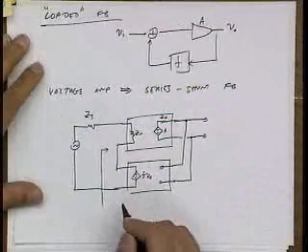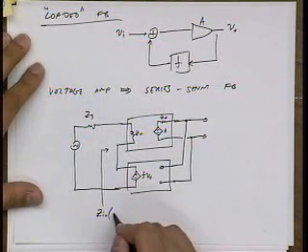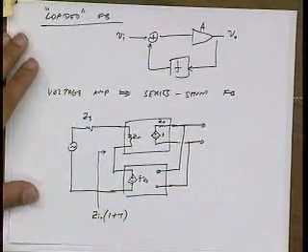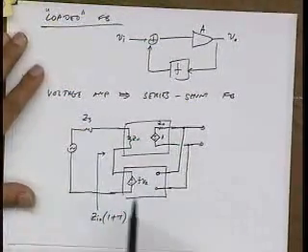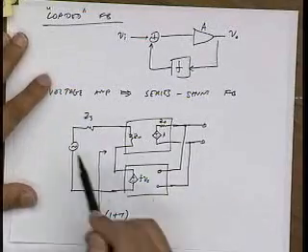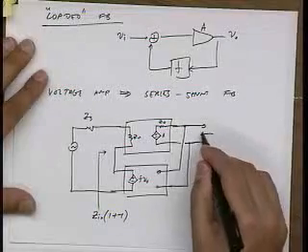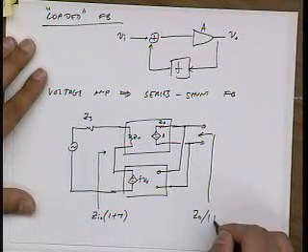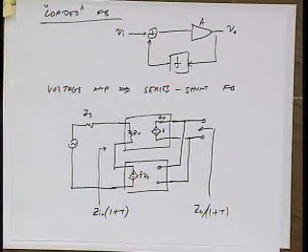The input impedance now is actually Z in, we'll show this, times 1 plus T, the loop gain. So I took my good voltage amplifier and made it an even better voltage amplifier, right? Or maybe I took a crappy voltage amplifier, and with feedback, I now have a very good voltage amplifier. And likewise, the output impedance is now ZO divided by 1 plus T. Okay.